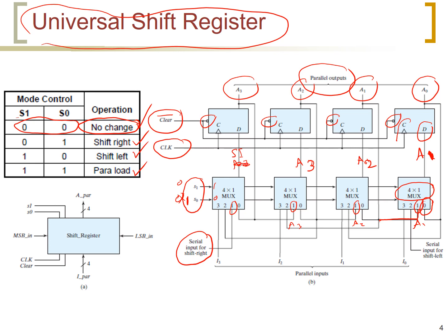Again, at the clock pulse, A1 will be loaded here, and A2 will be loaded here, A3 will be loaded here, and a new input will be loaded here. So as if we have shifted the bits from right to left. We call it shift right.